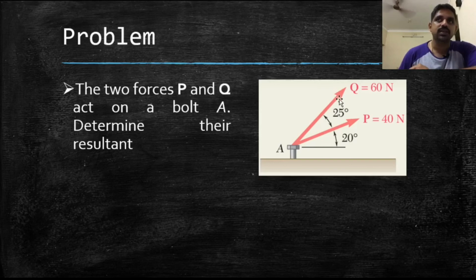So in this case, vector q can be represented as a 6 centimeter long line at an angle of 45 degrees, and on the head of q I place the vector p, and that p is going to be a 4 centimeter long line. So my resultant would be the line which joins from this point A to the head of the vector p, and we can measure that and also measure the angle associated with it.